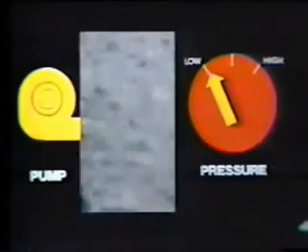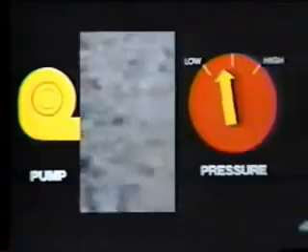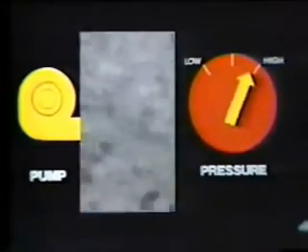Another property of air which is important to turbine operation is compressibility. If we attach a pump to our container, we can add more air molecules to those already there. Should we continue to pump air into the container, we would see the pressure rise. It's easy to see why. With more molecules, the number striking the wall at any single moment increases. Since each molecule exerts force on the wall when it collides, it makes sense that pressure would increase when more molecules are pumped into our container. So energy has been converted into pressure through compression.